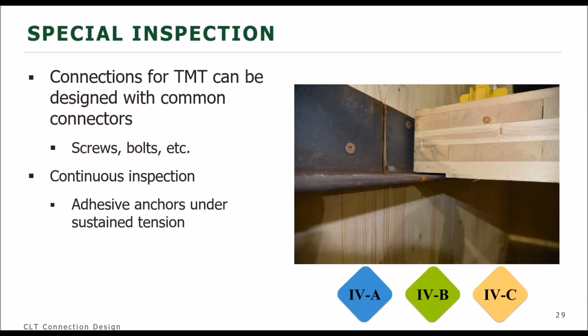So, things like screws and bolts: installing a screw or a bolt in a CLT panel is not that drastically different than installing a screw or a bolt through a glulam beam, for example. So that would only need periodic special inspection, but if you are using an adhesive anchor under sustained tension, that's something that would be necessary to have continuous inspection.